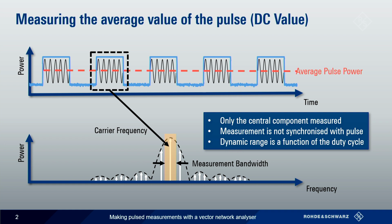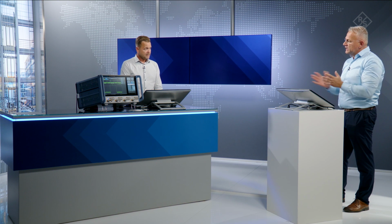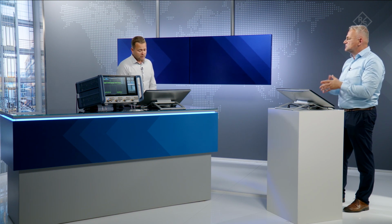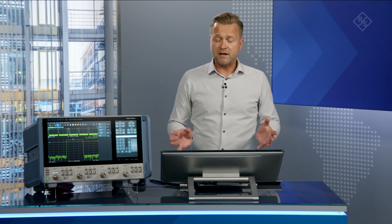So in this average technique, we're just focusing on the centerpiece, on the carrier frequency. Correct. Yep. And this doesn't put any specific stress on the test equipment. We don't have to trigger the measurement, but what we do have to do is be careful about the measurement bandwidth that we choose for the setup, because fundamentally the measurement bandwidth, the receiver of the network analyzer, is what's going to perform the job of filtering out the rest of this line spectra.